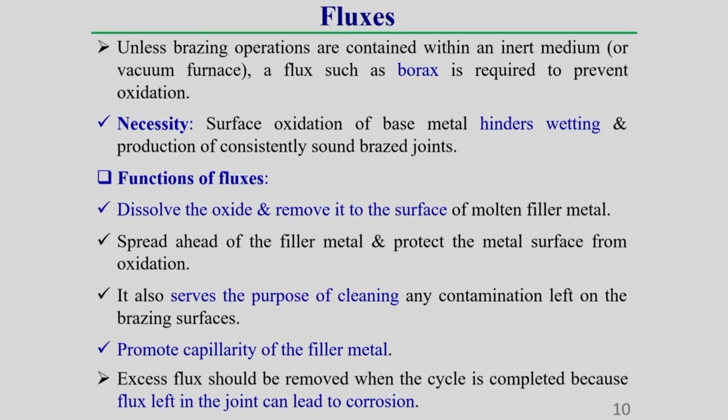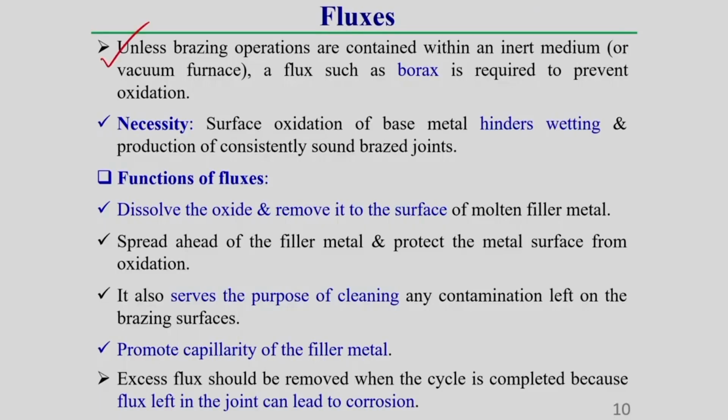Now, we will discuss what flux is and what its function is, then what the different compositions of fluxes are. Here one thing you should keep in mind: if the brazing operation is done in an inert medium or in a vacuum chamber, flux is generally not required. Except for an inert medium and a vacuum furnace, a flux commonly used is borax, which is generally required to prevent oxidation.